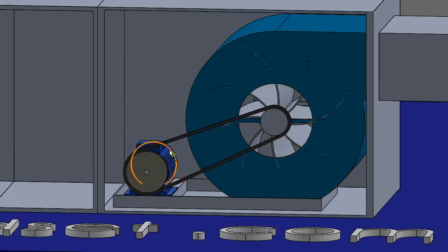So you can see here we've got an induction motor, and that's bolted down usually to a frame, because these are pre-built systems, and that's going off to the pulley, and then this is put onto a belt drive. And the end of the belt, this is kind of a rubber wire frame mesh belt, and that goes off to another pulley which is connected to the fan blades inside here.